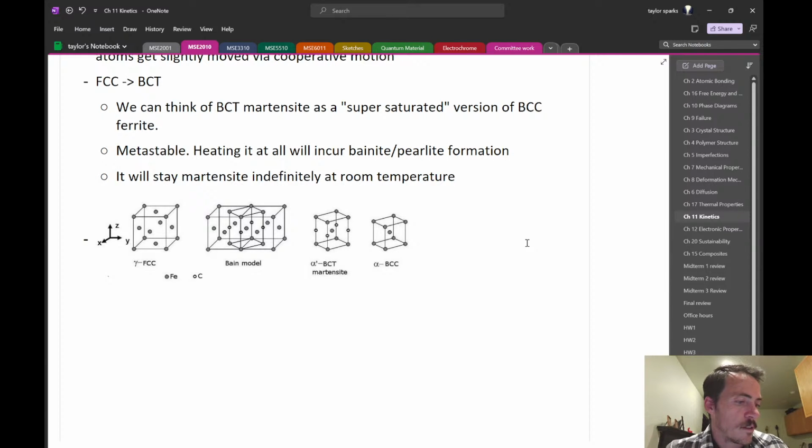How about this one? It says, what do you mean by effective area on the study guide? Is that just the A bar, A component, and the Y topic, or is there something more general that you want us to know? Yeah, that's exactly what I mean. I don't expect you to be able to calculate those. I would give you those if I want you to use it. But I think understanding that Weibull, when you do it on samples with a certain volume, that you have to transform that data in some meaningful way if you're going to try and extrapolate that learning from test bars to, say, freeway overpasses.